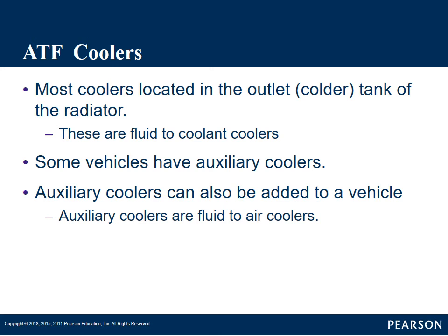That's important when we start talking about flushing coolers after we've done a transmission replacement or overhaul. That's important when we're talking about doing a flush and fill of a transmission. If it has those valves in it, we need to know it, and we'll talk about that when we get into servicing transmissions. Some vehicles will have one in the radiator and an auxiliary cooler.